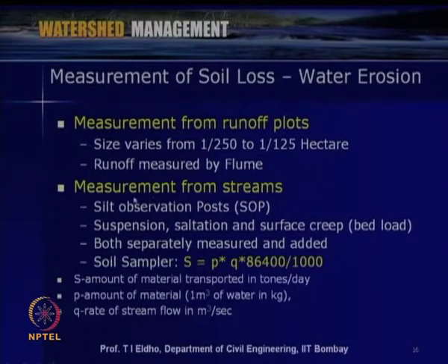And then in streams, measurement can be done using silt observation posts. The erosion in streams can be due to suspension, saltation, and surface creep, like bed load. Suspension and bed load are both separately measured and added together.